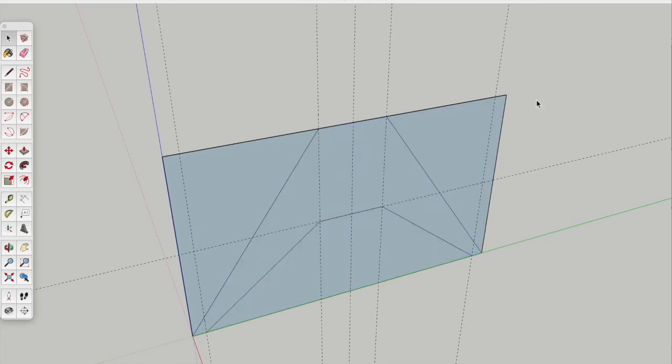And you may remember from SketchUp classes in previous years that by dragging from left to right, you select everything that's completely within your rectangle. In this case, nothing, so it won't select anything. By dragging from right to left, you select anything that the rectangle touches. So I can easily now select that area just by touching the corner of it, and everything is selected.